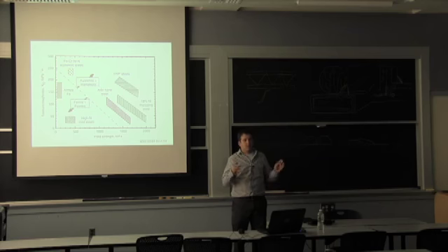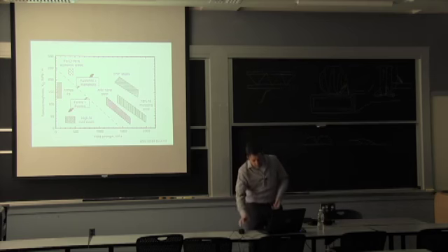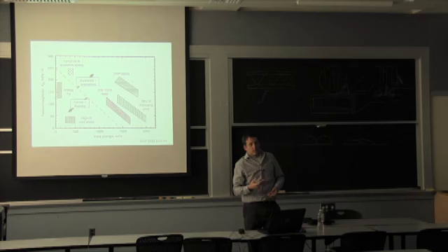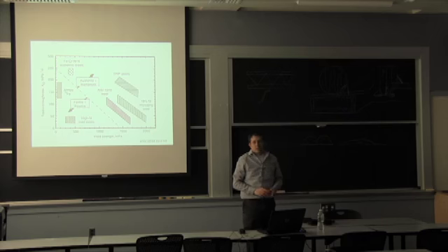very helpful. It's obviously more expensive. You have to go through processes to get your strain up to that level and still retain austenite that will transform as needed. But it's how you end up getting a toughness that's still above 100 KSI square root of inch